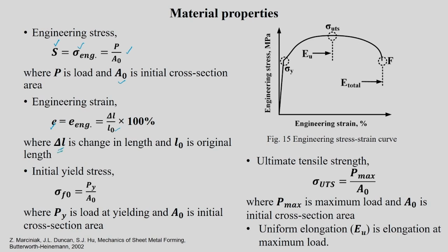Here one thing is very important: what gauge length you are going to pick up. That is why we say your gauge length L naught is a reference length to calculate any strain. If you want to calculate any strain, what reference length you pick up is going to be very, very important for us.